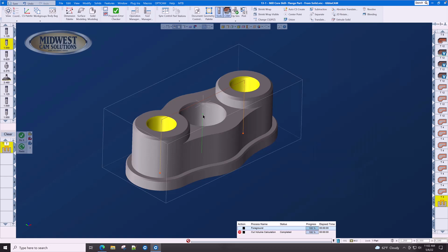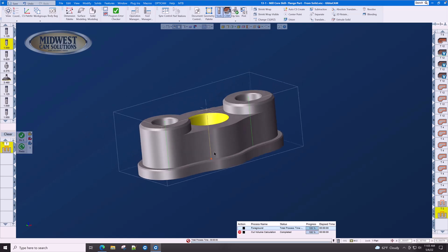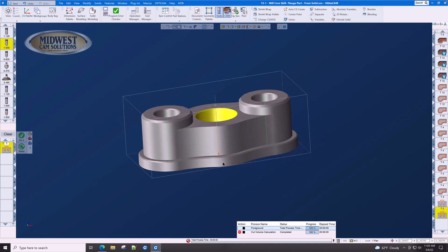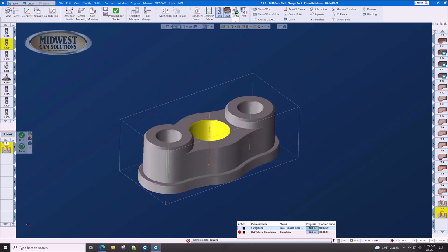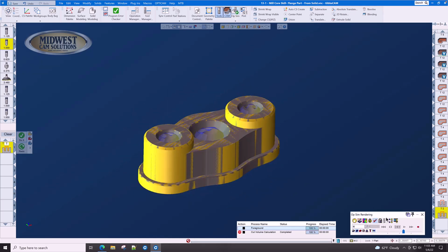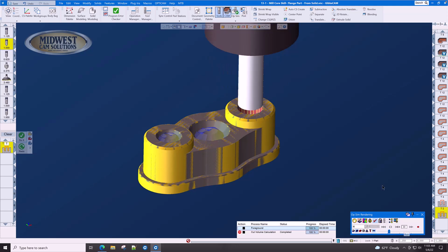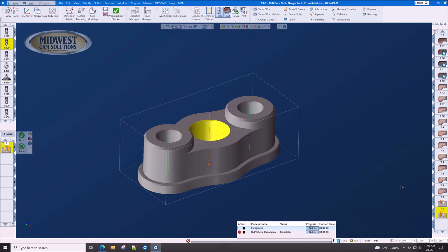When we click on this little stick here, the Hole Data stick, you'll see that GibbsCAM automatically placed the R plane, the top of the hole, and the bottom of the hole in the correct place. And if we rewind here and single block, or let's just run this in simulation, run mode, drill, drill, drill. You can see that GibbsCAM drilled these holes automatically with the proper depth.